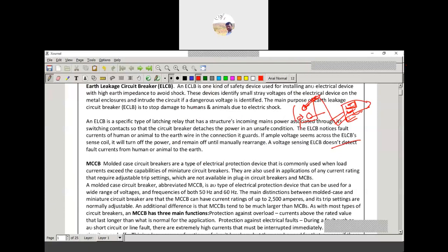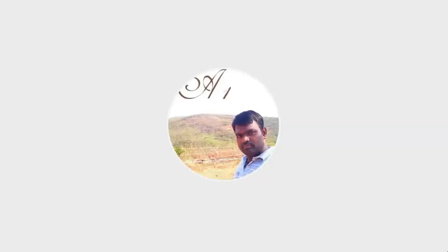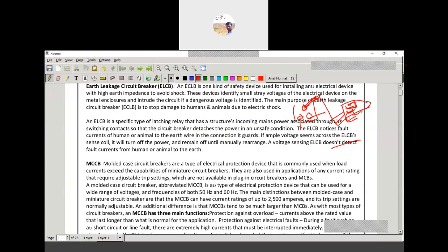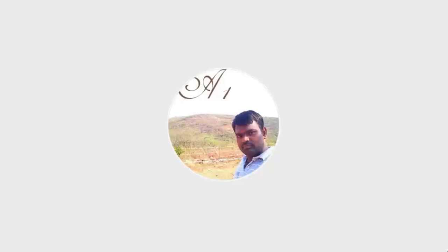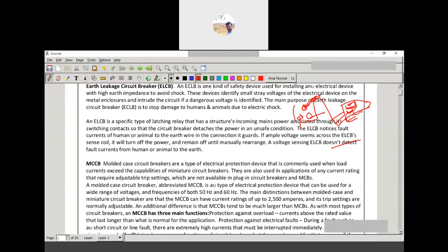So from that we have three pins: phase, neutral and earth. The phase is indicated by the red wire, the neutral by the black or, in some cases, blue wire, and the green wire indicates the earth wire. Only if we have the three wires can we protect ourselves. Not only the iron box, but also in machines.